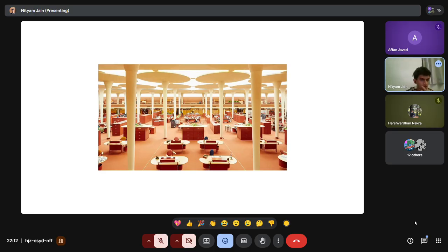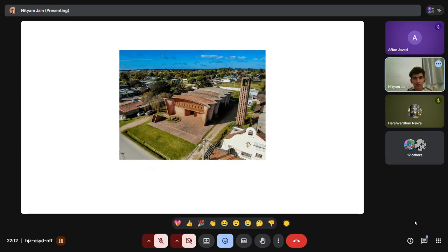That is what students had to figure out. And the top, where it's meeting the horizontal plate, has to be a fixed, rigid member. Thus, you cannot have a thin profile there. You have to make it broader just to have more strength there.